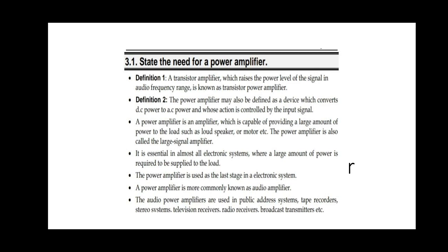So stability can be increased by using negative feedback. The product A beta is greater than unity, so AF is 1 by beta. So gain depends only on the feedback fraction beta, on the characteristic of the feedback circuit. The beta network is a resistive network, therefore it is unaffected by changes in temperature, variation in transistor parameters and frequency. So the gain of the amplifier is extremely stable.